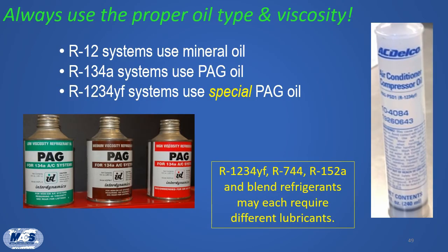And when it comes to the type of oil to refill the system with, always use the proper oil type and viscosity. R12 systems used mineral oil, and R134A systems use PAG oil. But the R1234YF systems use a special type of PAG oil that's not the same as R134A. So make sure you don't mix them up. Also, R1234YF, R744, or R152A and other blend refrigerants may each require different lubricants. So there really is no AC oil that fits all systems.